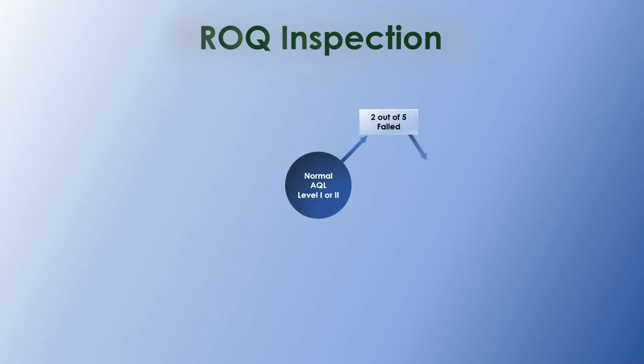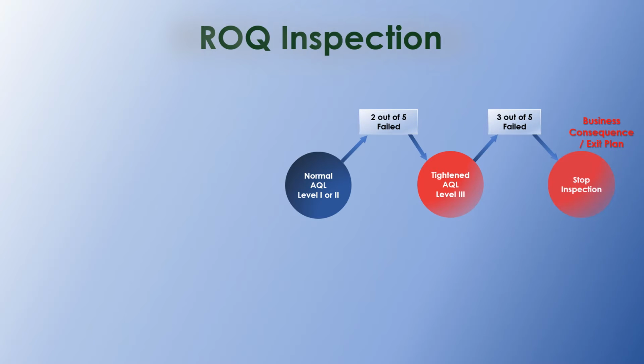The first ROQ method involves inspection based on the ISO 2859-1 switching rules. It starts after production inspection, applying AQL statistical sampling level 1 or 2, depending on the brand's requirement. It then moves towards tighter sampling with every degradation in performance, ending with a business consequence either at the product, factory, or supplier level. Once satisfactory improvement is demonstrated, inspection activities can then be restored with tightened sampling.